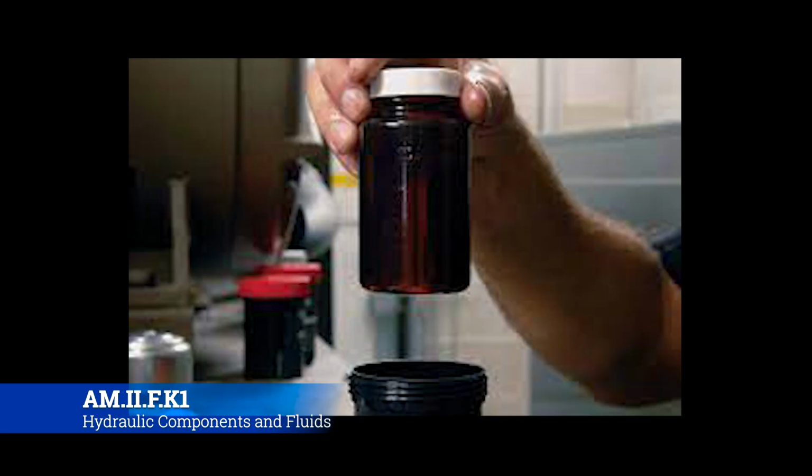Okay, so a couple other notes on hydraulic fluids: you can't mix and match. The chemical basis of all three of these types of hydraulic fluids are very different from one another, and that means that the equipment that they're going to be going through, the seals, the hoses, all of that is going to be tailored to that particular hydraulic fluid, and so you don't ever want to mix and match them. And on top of that, they don't necessarily work together very well.